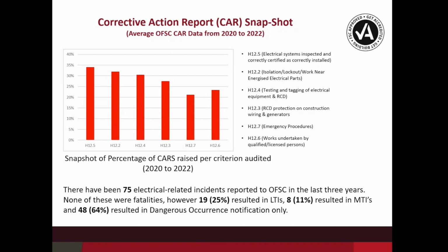The difference between, as an example, when an RCD trips on overcurrent versus an actual RCD trip, is that they go into 2 different positions. One's in the fully closed or fully open position. It'll trip to the bottom, and the other one will trip to the middle, which means that it's shown an RCD trip. So we need to understand, before we go doing too much work in that space, what was the source and the reason for the trip.